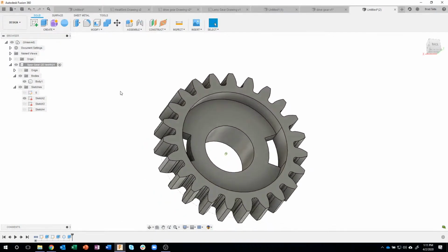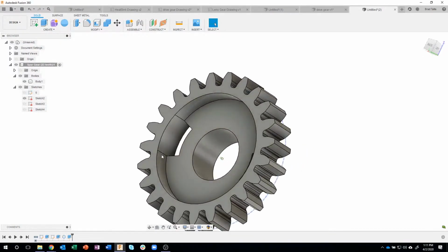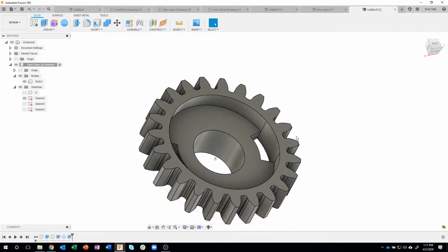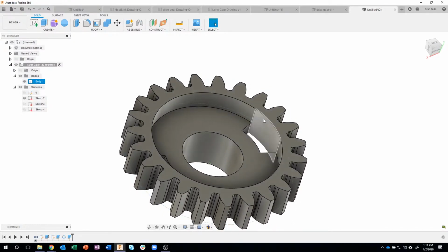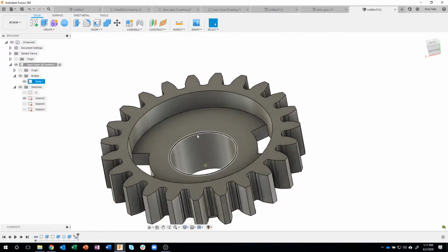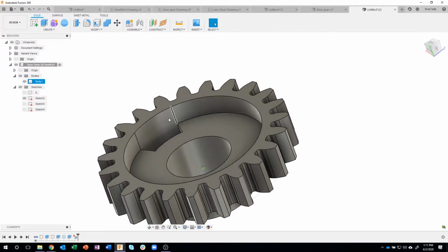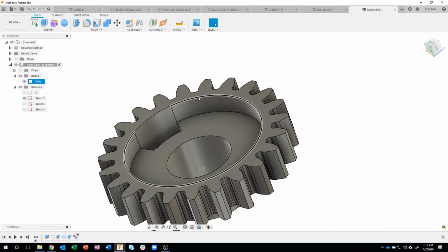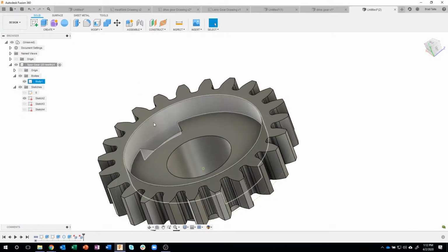Now, you might run into this. You'll notice that there's these edges right here. Now, I could leave those. That's totally fine. I could also click on that face and hit the delete key, and notice that it basically healed that region. Now, the only thing I can think of is that the curve of the circle and the curve of the slot were just ever so slightly different, maybe. And so mathematically they didn't match up, so it left that face.